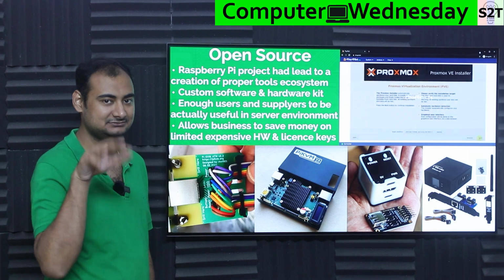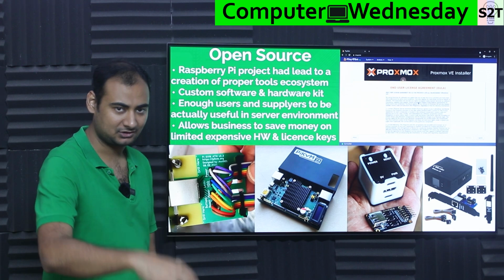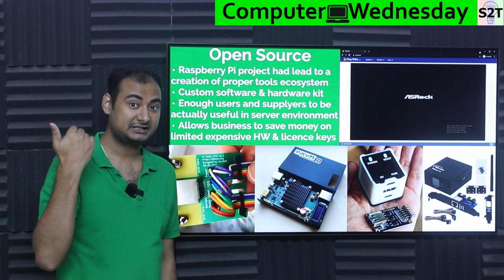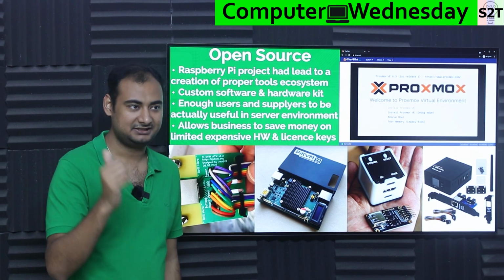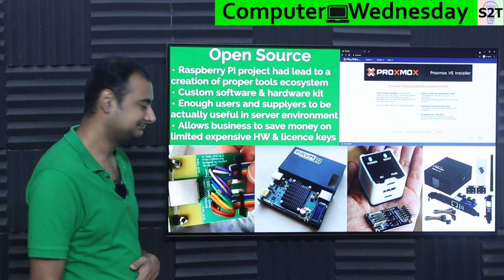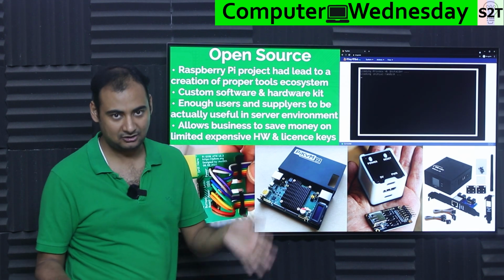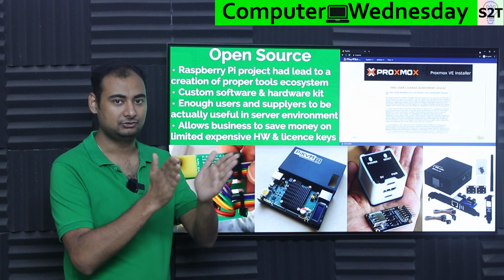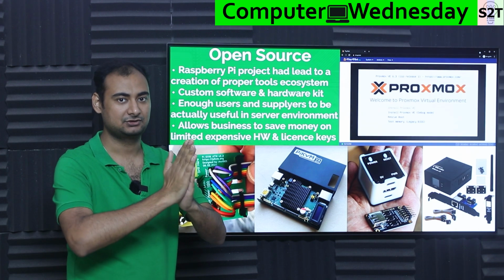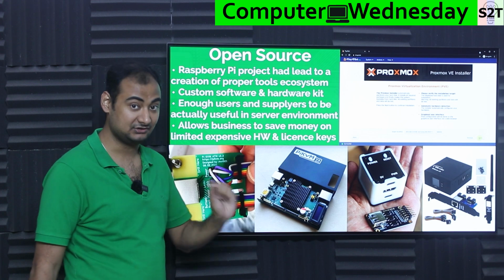So what if you take the GPIO pins and split them inside the computer? The idea is you put this inside your computer box. This goes into the ATX power control circuit, meaning on off. LED, you can get the status out of it. So power LED, hard drive LEDs, restart button, power button, all that jazz. You can get the data out of it. Because again, general purpose input output pins can be configured in such a way that they are output, as in they will turn on, like this for your reset switch, or for hard reset, 5 seconds. You have to do it for 5 seconds for hard reset for PSU. So all that is possible with this because it has GPIO.